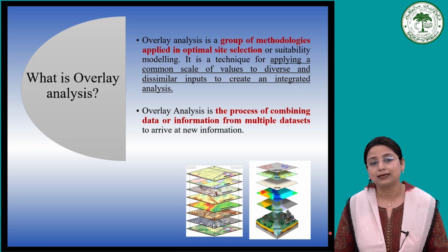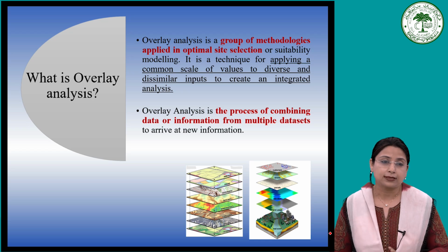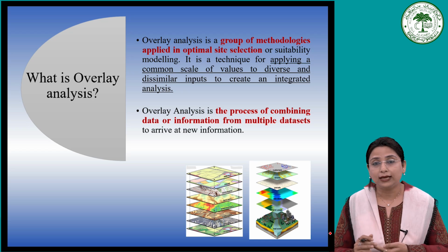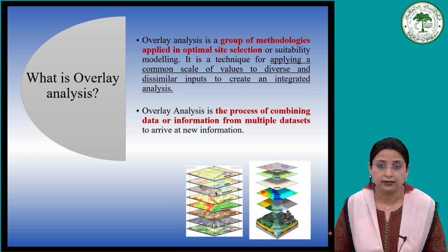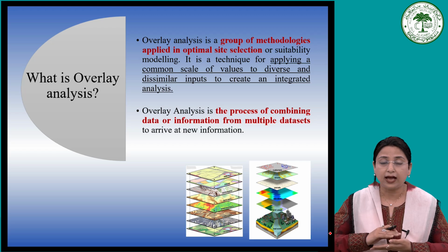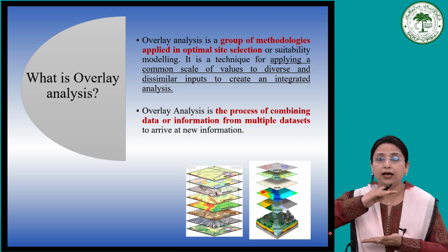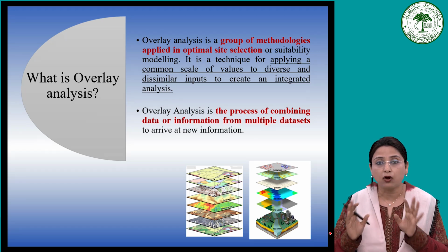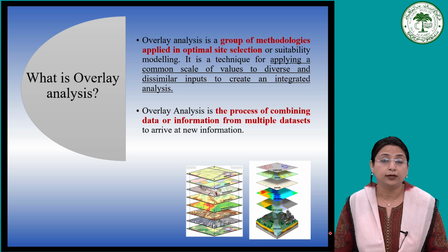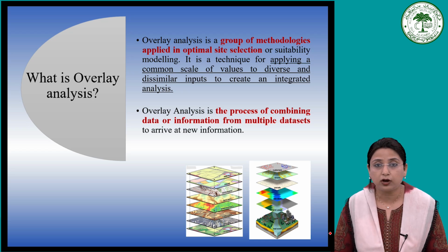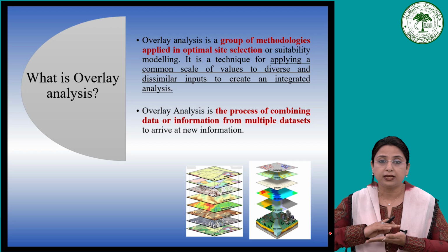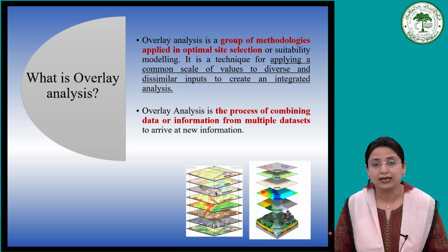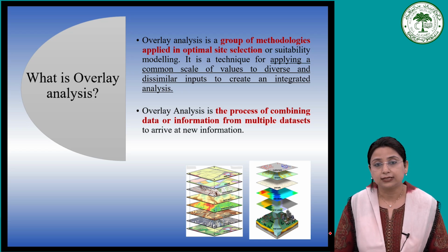Before discussing the case studies, I would like to discuss what overlay analysis is. When we talk about overlay analysis, as the term signifies, overlay means we have to superimpose one upon the other. We have to give the input layers to the software environment, most importantly the GIS environment, different input layers one upon the other, so the important attributes can be integrated for a certain task.